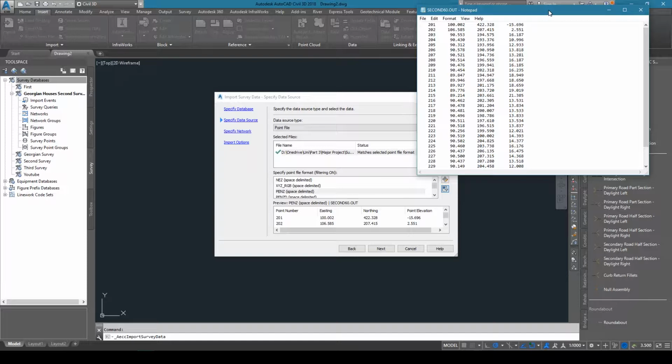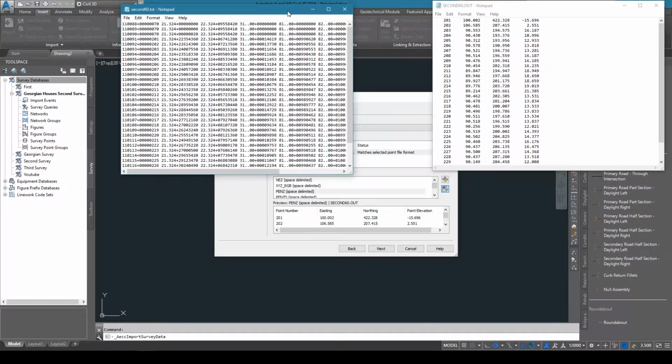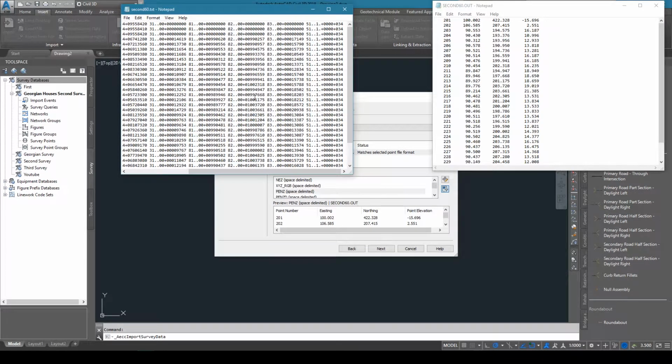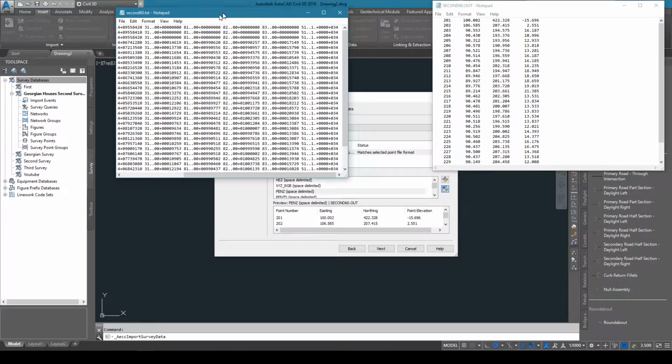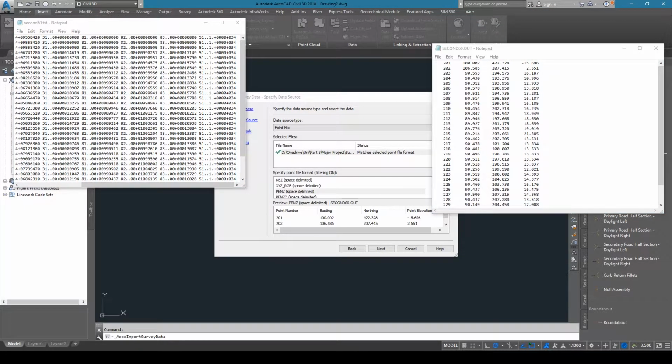So just a quick note about these file types. The final file type I received after reducing my data was a .out file, which had the exact coordinates and heights in it. I'd started with the raw data from the survey, which looks something like this. Each column represents a different measurement, with the first being the point label, but really it's unusable for one main reason, and that is that the data is relative to the instrument. Therefore, should another survey data set be put into the model with this one, the points would not coincide correctly, therefore reducing the accuracy of the model.